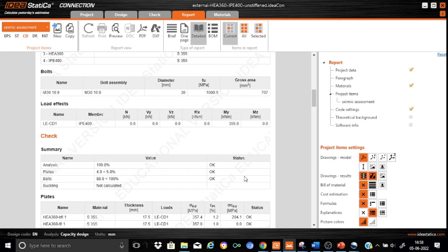As you will find, the seismic assessment hardly takes 5 to 10 minutes. But what is very important is that the seismic assessment cannot be straight away done using Idea Statica, because the engineer needs to know the sequence of dissipation, or the strength hierarchy, of the various components of the joint if he wants to get an insight into the overall performance of the joint. So in my opinion, I have spent almost as much as 1 week for the homework calculations.